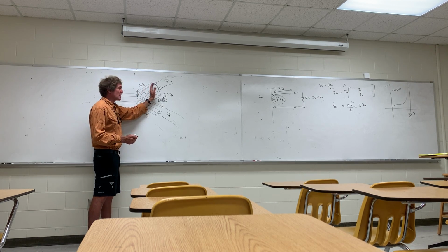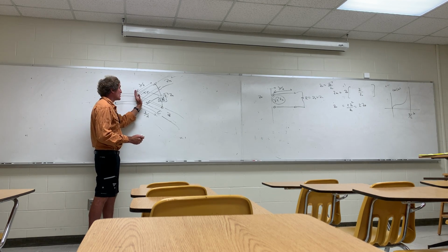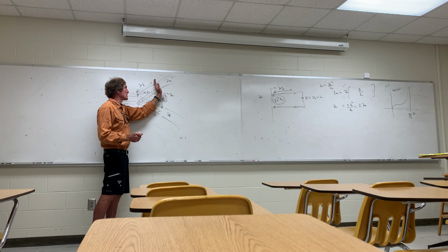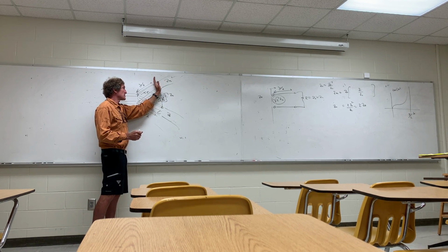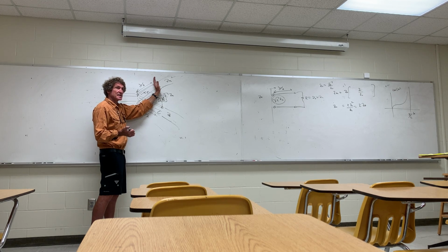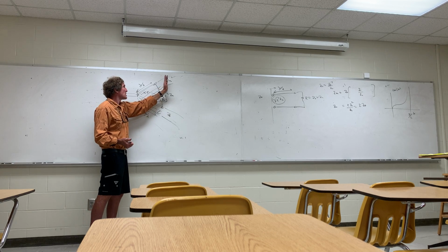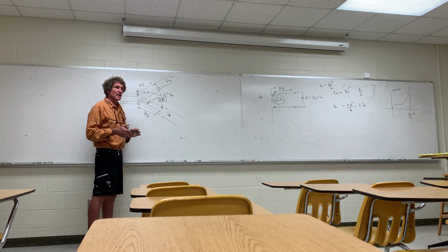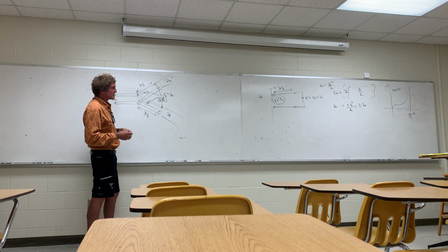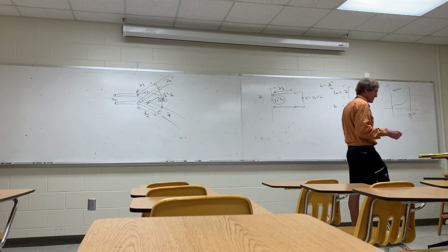So if this second line wasn't here, you would have reflections, right? You would also have some reflections if it comes this way and hits this Z naught here. There's a reflection coefficient there that isn't exactly 0, right? But when I put this resistor on here, 2 R naught, then the reflection coefficient looking at this port will be 0 as well. It's more advanced, more work to do that through it. I'm not sure it's worth it right now.